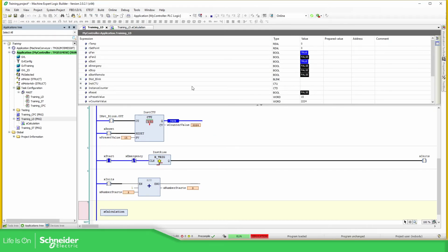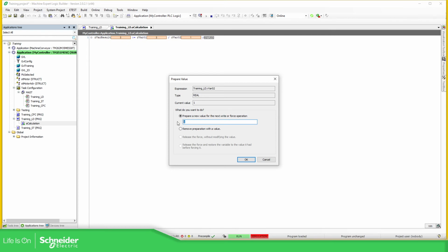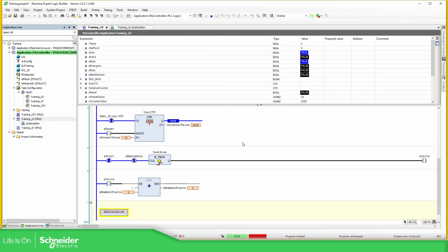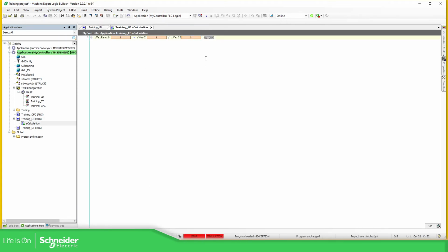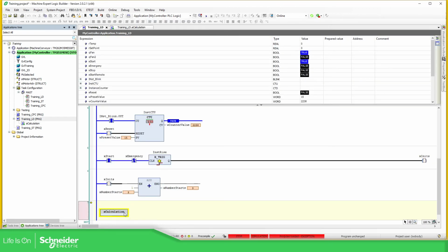Online change. PLC is in run. Okay. Then I'm going to define this value 0. Okay, it was an online change, not an online load, so I'm going to modify this. So now we can see the behavior. You can see here, this one is in yellow, indicating there is something wrong. Okay, program load exception. If we go over here, this will be the problem, and it doesn't matter if I start and run, it just doesn't allow me because we have an error here.